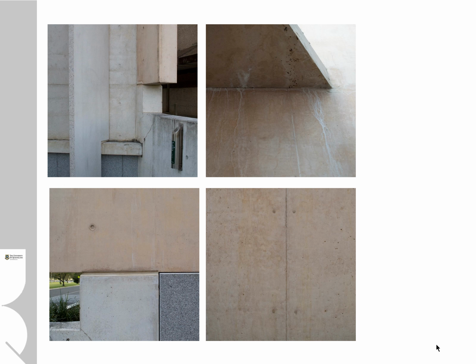So in this instance, in the top left hand corner, you can see from that small rebate there's an uncontrolled crack coming up from there through the wall, and that's attributed to the differential movements between that rebate and the large concrete in between, and the geometry of the concrete coming into that. It's a very easy mistake to make. It's not really a mistake, but more a bit of an oversight.